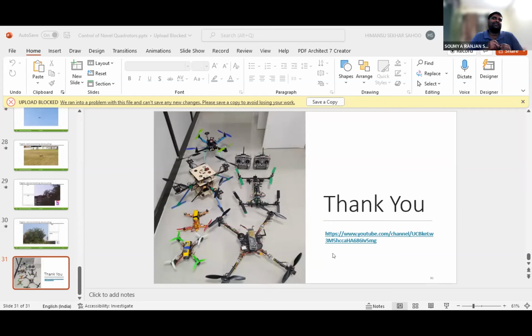A good experiment that you should do is to have a small setup in the lab, which can use some hydraulic jacks, etc. You can have a platform which can do pitch and roll and also heave, going up and down. And if you can land on that, that will be a very interesting thing. We have tried, and we have found that it is very difficult to do.